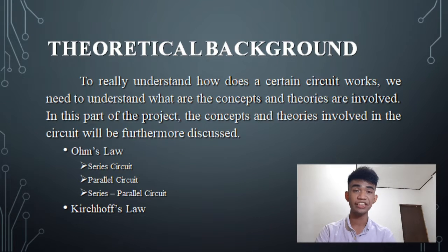Also, Ohm's law has different approaches when it comes to series and parallel circuits. In series circuits, where there is only one path, the current is equal all throughout the circuit. While in parallel circuits, where there are two or more paths, the voltages are equal. In a series-parallel circuit, the concepts of series and parallel circuits are combined to calculate the values of each of the individual resistances, voltages, and currents.